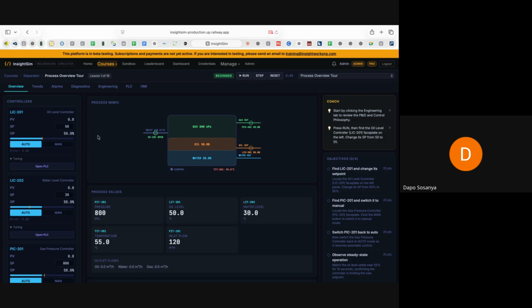It is the wellhead that is feeding this particular pipe, and you have this inlet valve. You can see the capacity of that valve. It's an XV, a block valve, and it is opened. So it's dumping everything in this tank, and this tank uses mechanical principles to separate all of this, and then separating the output. So you can see how the process works.